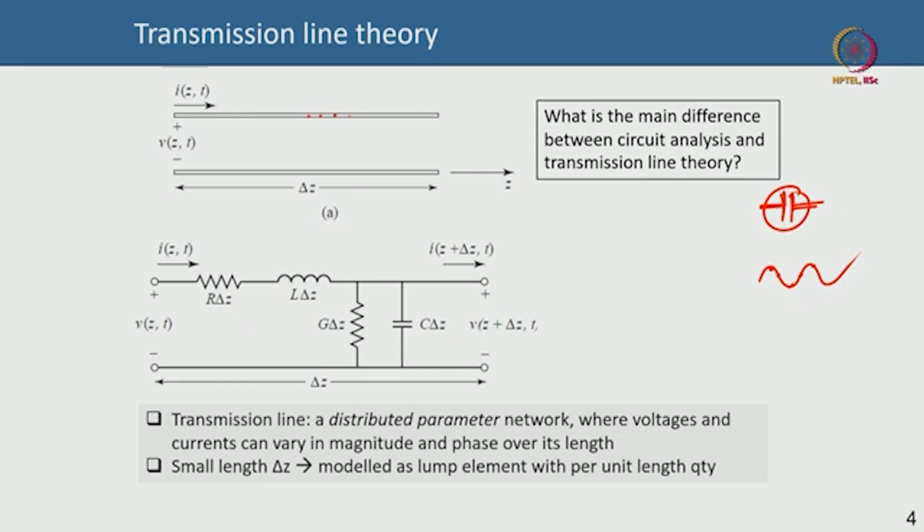On a single capacitor, for instance, the magnitude and the phase of the electromagnetic wave or the RF wave can actually vary with respect to time, with respect to position. So, it makes it very complicated. That is why you have to take the help of distributed parameter network, where you do not discretize them in a lumped element, you treat it as a distributed overall parameter.